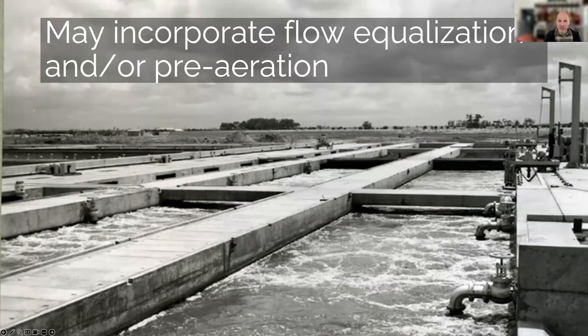When you have these, aeration is a must, because otherwise that stored influent can go septic prior to treatment, and again create offensive odors and things like that. So this is the only other portion of preliminary treatment where you might get some biological activity going on, depending on how it's set up, because essentially you're pumping air into this system.